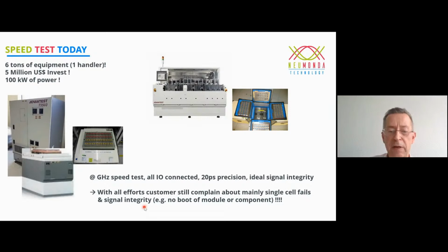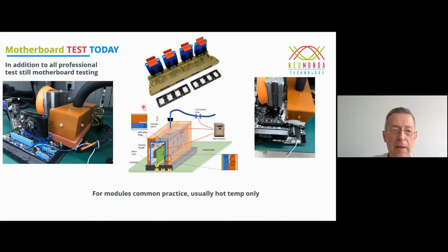There are still signal integrity issues. The DRAM boots maybe 1 or 2 or 3 or 4 times. The 5th time, the server or motherboard cannot boot. So this is the reason why a lot of companies, in addition, in their backend, are doing motherboard testing.